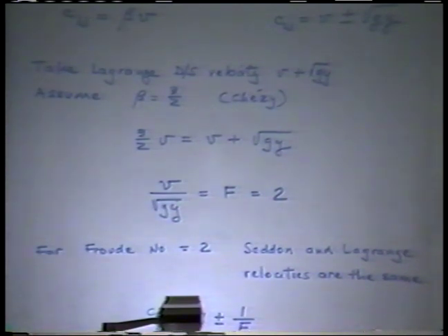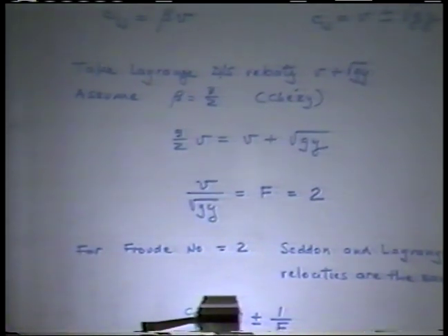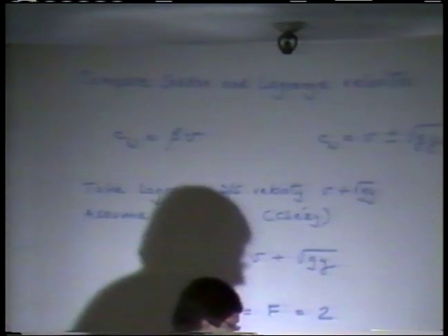So any disturbance that is created by whatever means, and you know there are many possibilities for creating disturbances, boundary conditions, and so on, these disturbances will be amplified to the point where they look so uniform, and they are like jumps in the channel. They look like this. And these are the so-called roll waves, which typically depict the onset of instability.